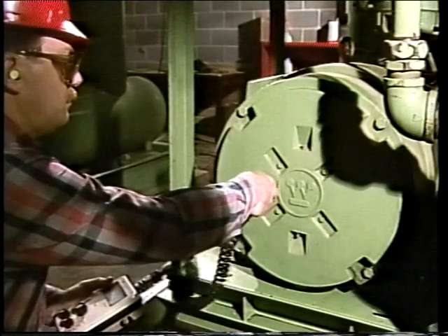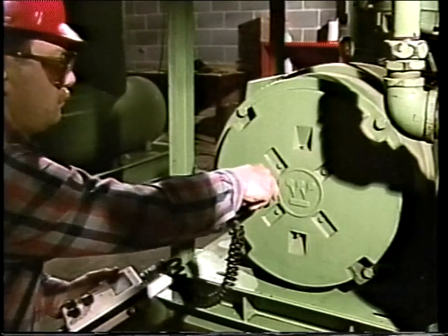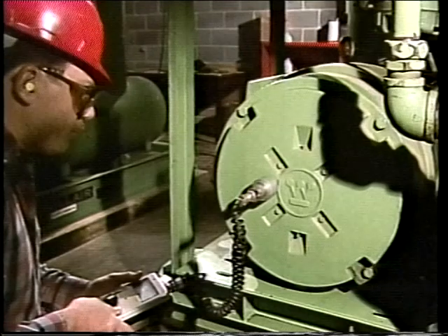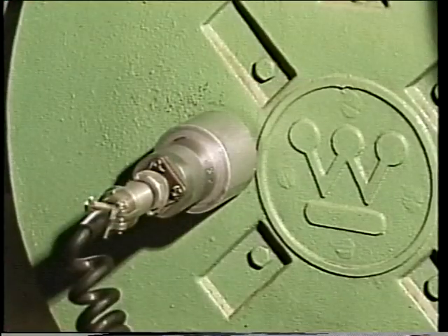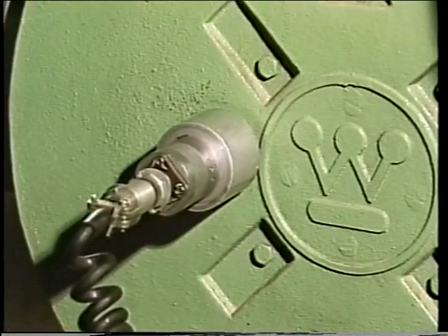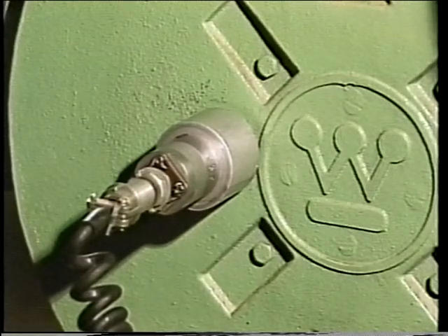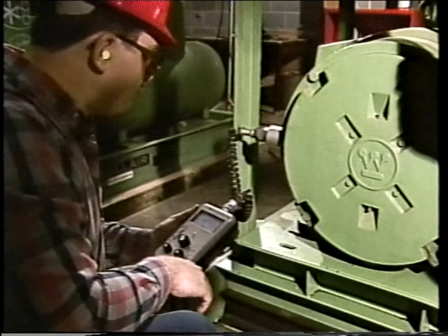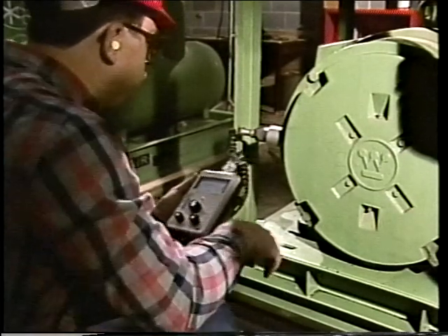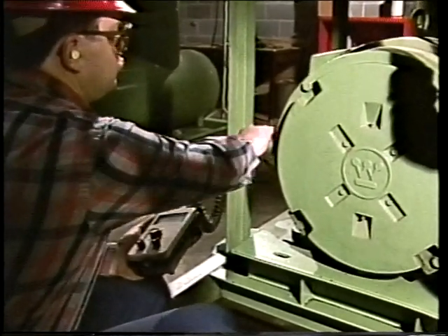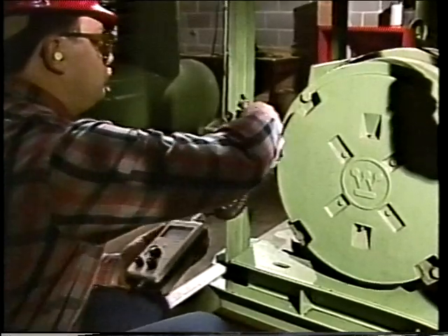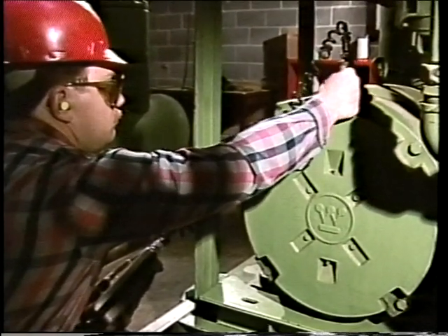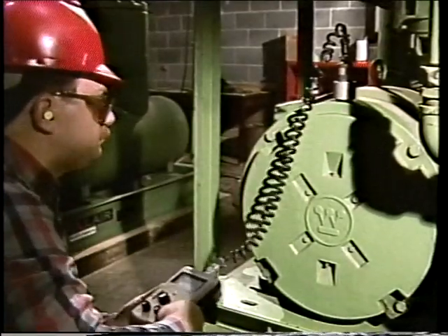If the machine being checked has more than one set of bearings, each bearing should be checked if possible. Also, each bearing should be checked from 3 different directions. For example, this horizontal shaft should be checked from a point located parallel to the center line of the shaft, then perpendicular to the center line in the horizontal direction, and finally, perpendicular to the center line in the vertical direction. Checking from these 3 positions will provide all the information necessary.